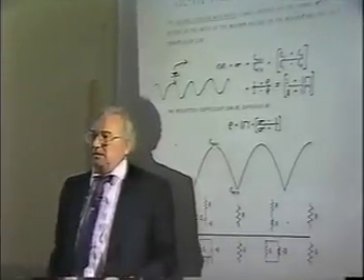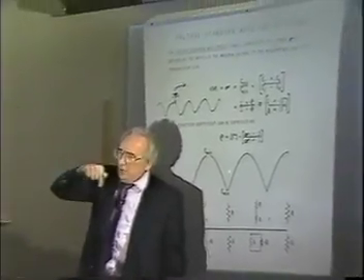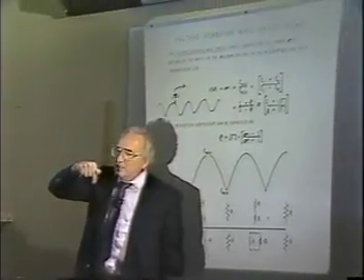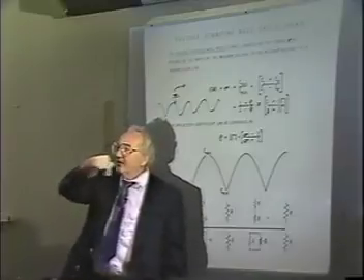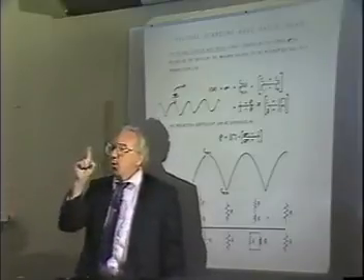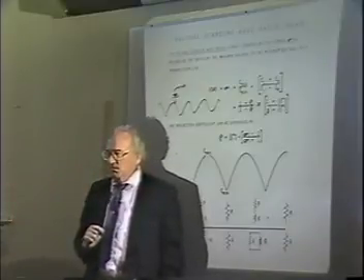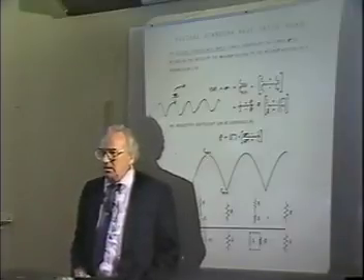Same thing. Because all you see on the line is a probe that would go down and check the electric field intensity; no matter where you move it, as long as you keep that probe the same distance into the electric field, you see only one signal. No standing waves. Now, is that clear?